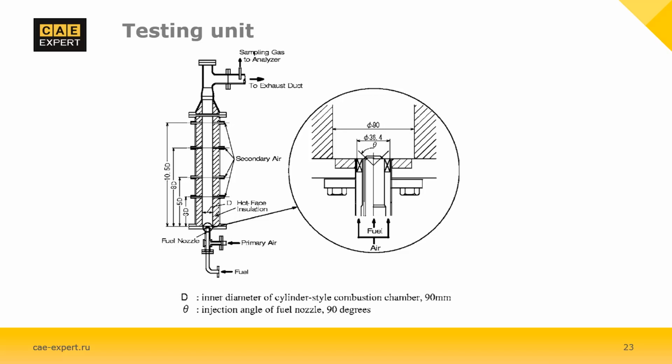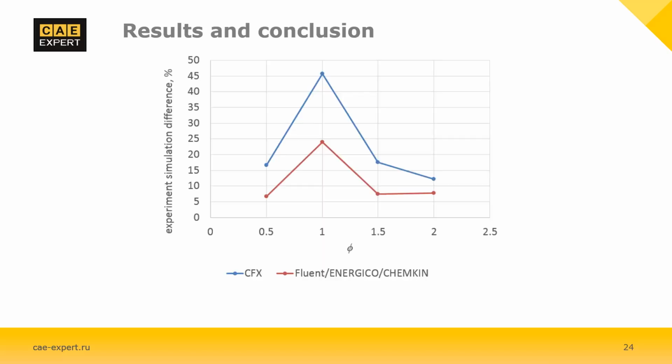The combustor exit gas temperature was set to 1773 kelvins, and the fuel injection velocity was set at a constant value of 77 meters per second. The cross-sectional flow velocity of total air was 0.53 meters per second at the temperature of 273 kelvins, basis case.